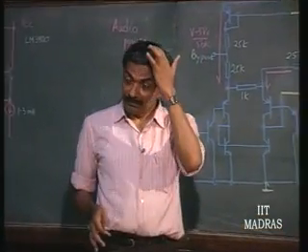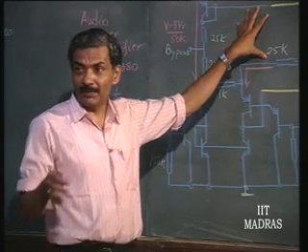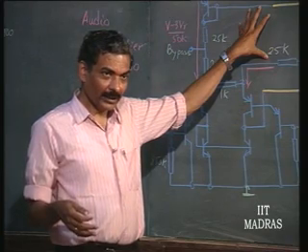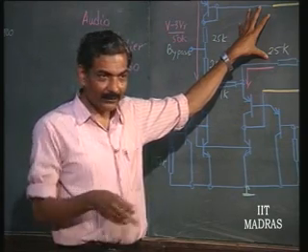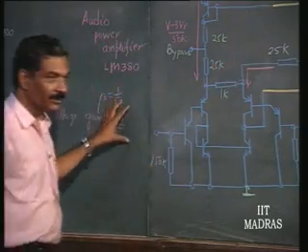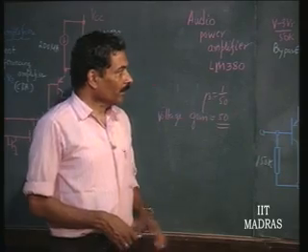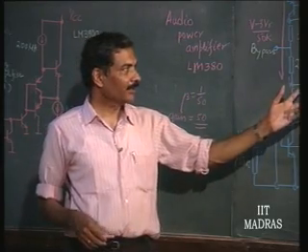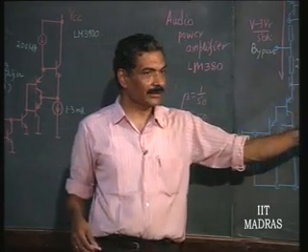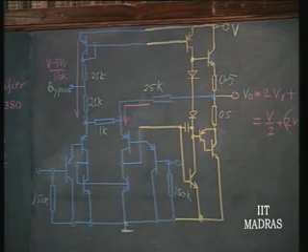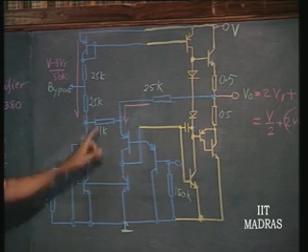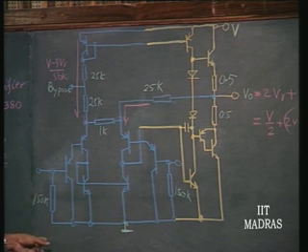Again, I would like you to now, for the entire stage, now that you know the component values, assuming beta equal to 200, evaluate the open loop gain, as well as the loop gain of the structure, and show that the gain is very nearly equal to 50. Once again, you can find out the input impedance etc. from the same strategy. What is it? It is going to be effectively, what is the input impedance? Effective emitter resistance here. Essentially, emitter resistance is made up of only 1K and beta, so beta squared, and of course 150K will be shunting that. Is it clear?